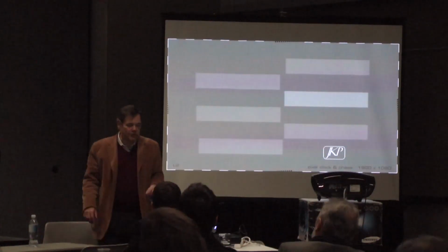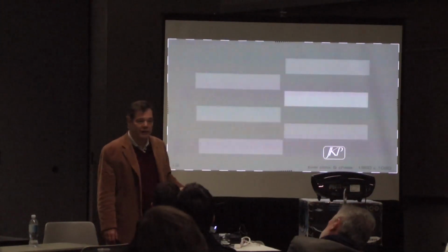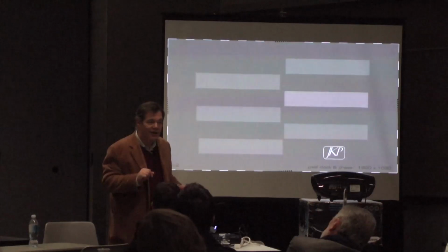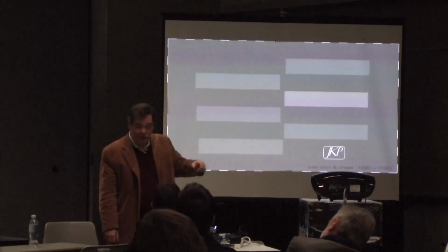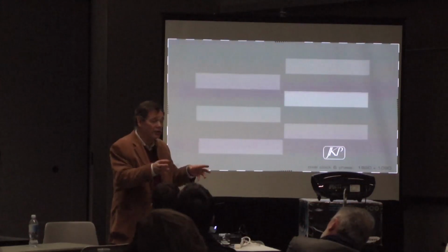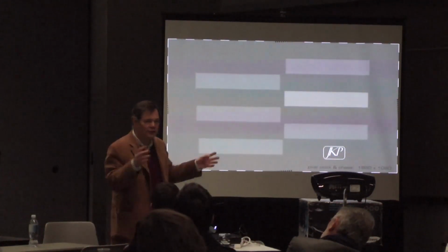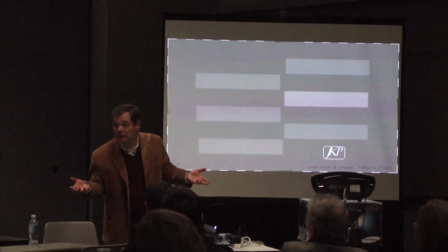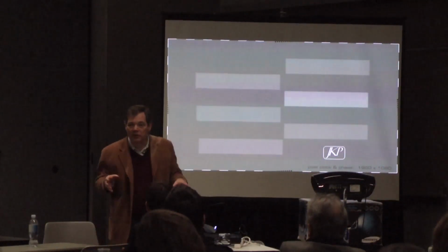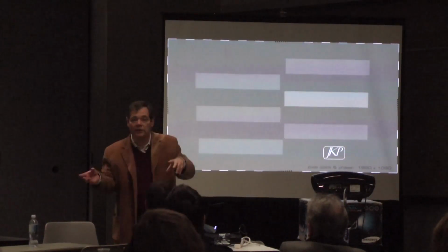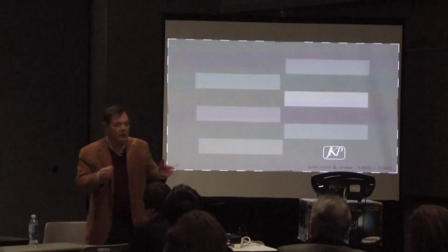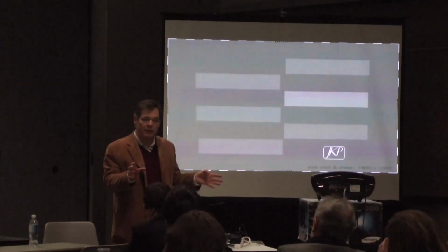In the majority of the test patterns I created, I actually labeled left and right, so that if you block the left eye, you should see the letter R. If you block the right eye, you should see the letter L. And that makes sure that your glasses are in sync with the picture. So almost all of my patterns have an L and an R in them. The left panel is labeled left and the right panel is labeled right. But all of the same test patterns that were critical to determining what the display is doing in 2D, I now have in 3D.